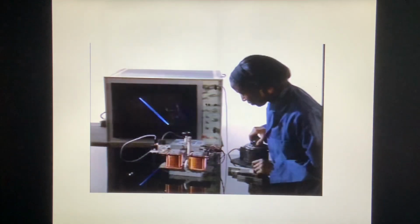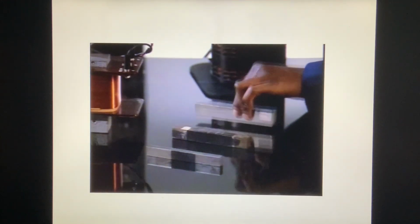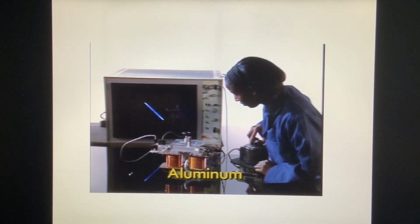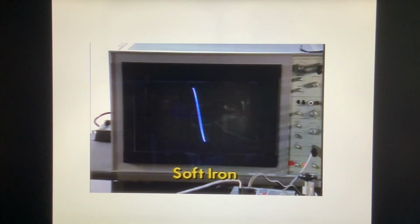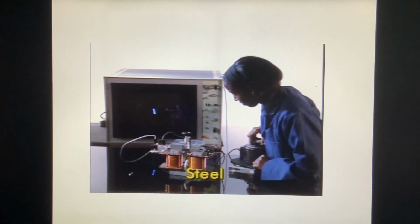The vertical and horizontal scans are initially in phase, and a straight line is displayed on the oscilloscope. If this piece of aluminum is placed between the ends of the two coils, there is no effect on the currents. If it is replaced with a piece of laminated soft iron, the second current lags behind the first, and the straight line becomes a loop. A piece of steel causes an even greater time lag between the two signals.